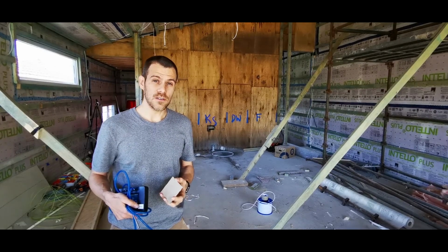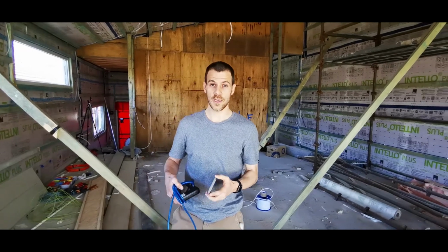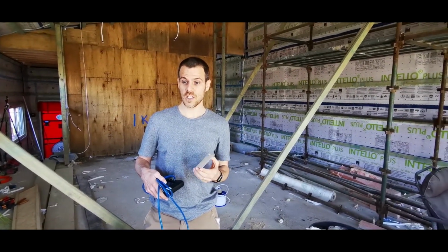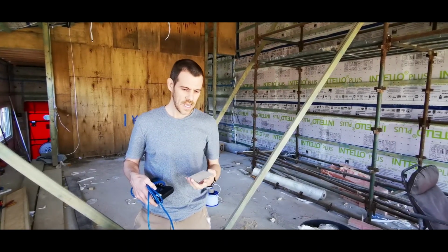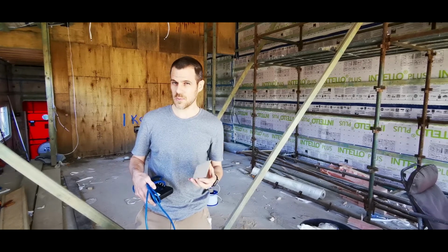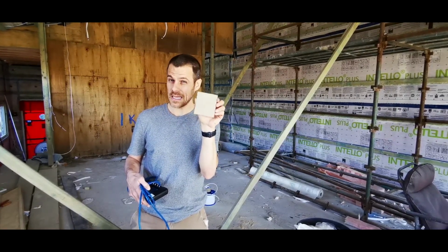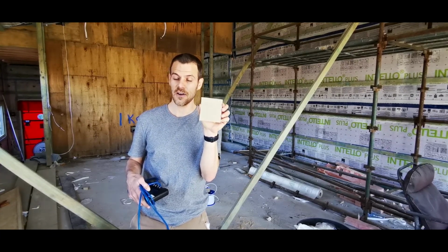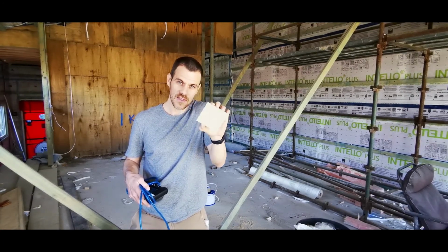You can do a conversion. The blower door software, in fact the manometers, in real time can convert between air leakage and estimated leakage area. How much leakage area, roughly speaking, does this represent? For this particular house, it's probably a combined whole of something like this size for the entire house. You're allowed this much leakage for the entire house. Does that blow your mind? That's all you're allowed for this entire place.